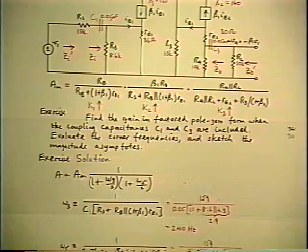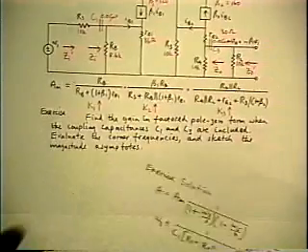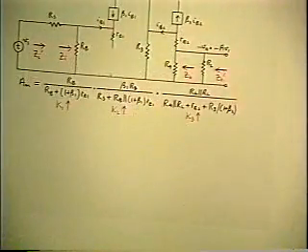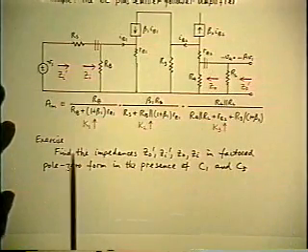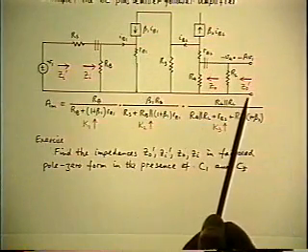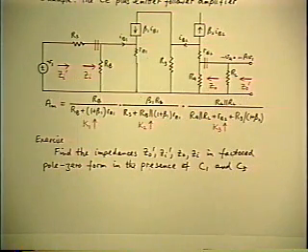Okay, what we've done now is, for this especially simple case where there was no interaction between the two reactances, we can get the result by putting them in separately. So we get two inverted poles. So the final step is, now that we have the modified gain expression, you can use the input and output impedance theorems to find input and output impedances in this case.